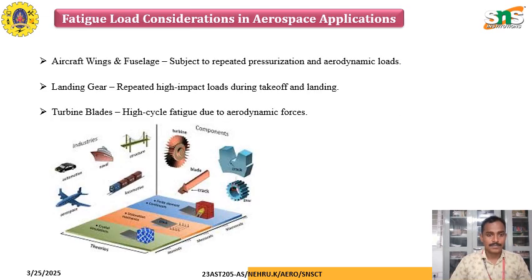Let us look at a few examples of fatigue loading in aerospace applications. Aircraft wings and fuselage are subjected to repeated pressure and aerodynamic loads, which lead to fatigue failure. In the landing gear, repeated high impact loads during takeoff and landing, with high temperature or sudden impact, lead to landing gear fatigue failure. Next, turbine blade fatigue cases: high cycle fatigue due to aerodynamic forces, and low cycle fatigue due to centrifugal force and high temperature in high speed operation.